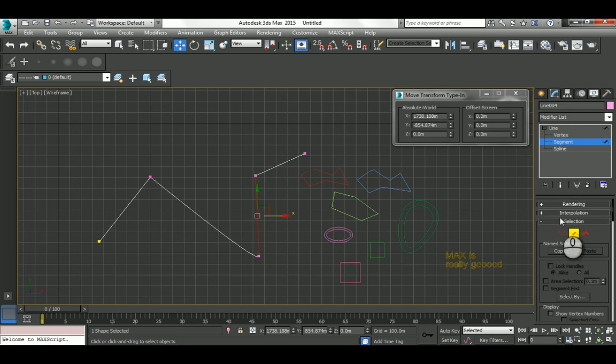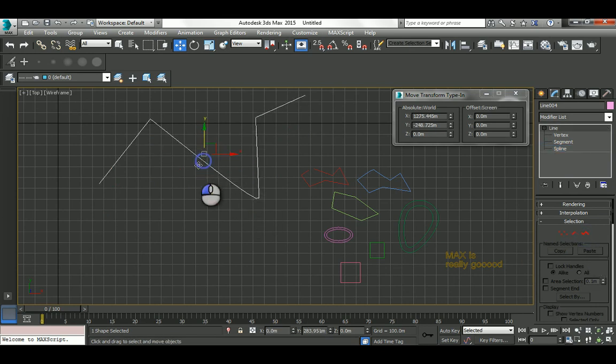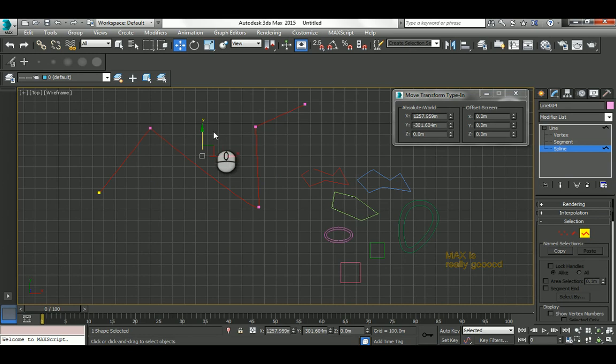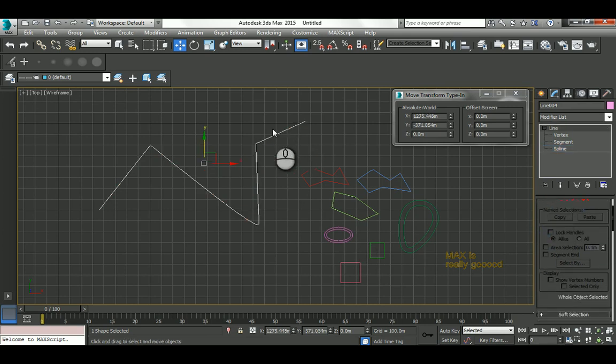And finally, Spline, and when you select it, it's going to cause a little bit of confusion. It's going to select all the lines for you, and when you move it, you're going to move all the lines with it, and now you're going to kill the basic understanding that you just have for the difference between sub-object modeling and object modeling, because if you turn off this, all the object will move. If you turn it on and select the full Spline, all the object will move. Now you have every right to be confused, but in order to make you understand this, I can turn this off, and again, the whole object is those 1, 2, 3, 4, 5 or whatever amount of segments.